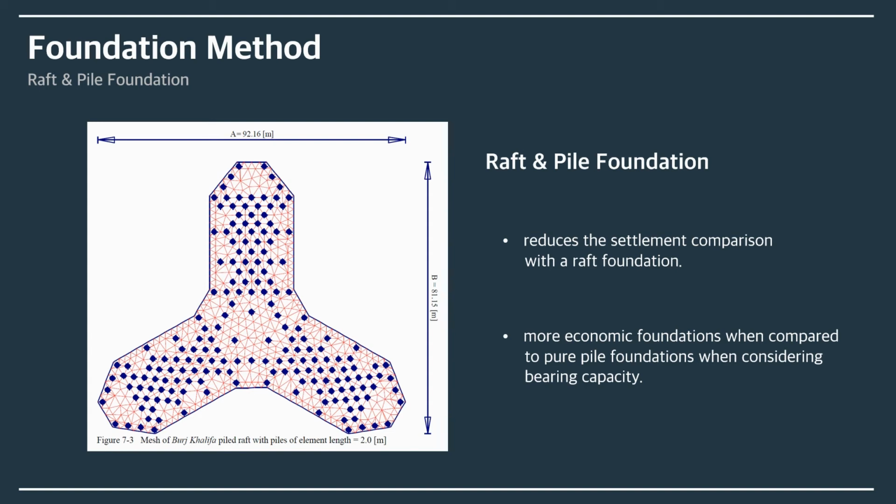Using this method, there are many benefits. First, the piled raft foundation reduces the settlement compared with the raft foundation. Second, the piled raft foundation is a more economic foundation compared to a pure pile foundation when considering bearing capacity.